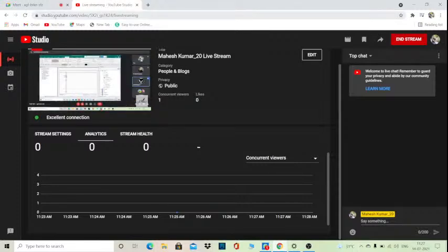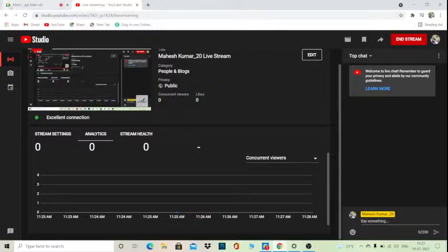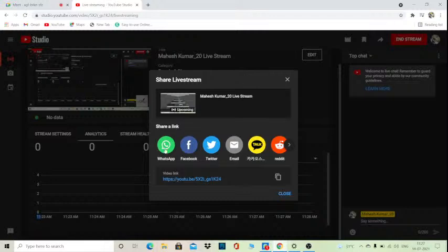So we can use the option called single wire, and select and drag. That's it. So this circuit is complete now. For this we can give terminals X1. The same way, we can make some cables also using the cable option.